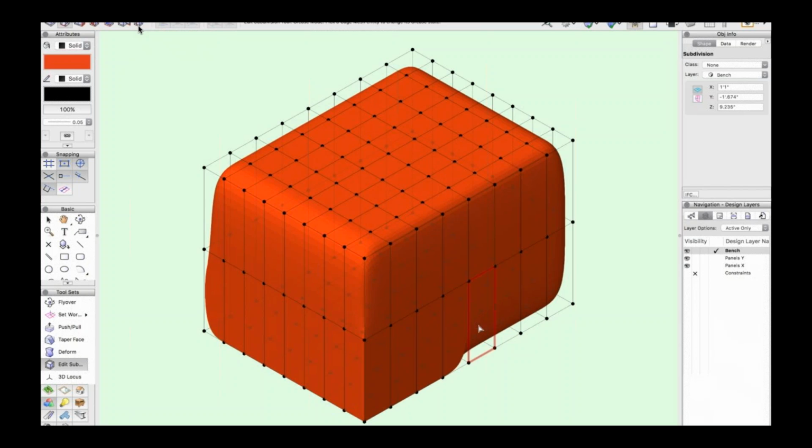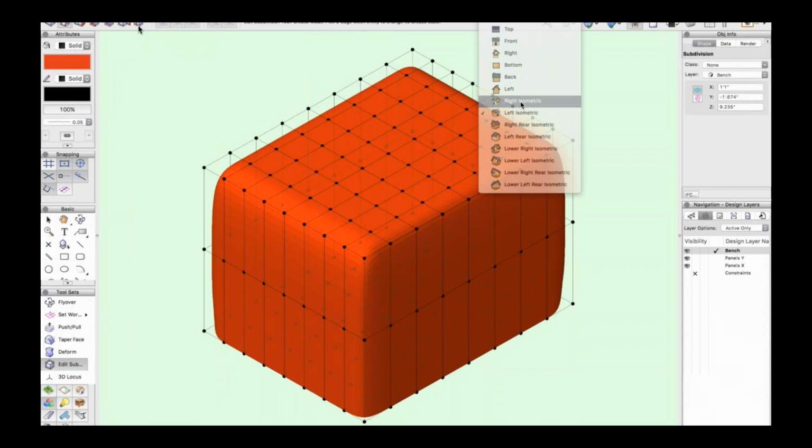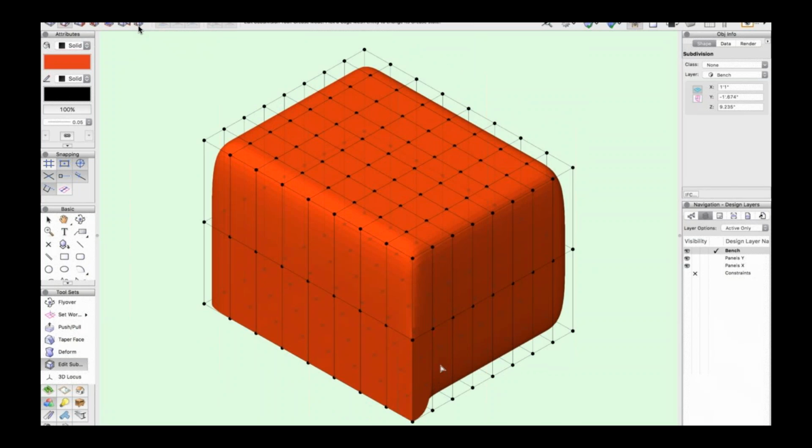And what I'm doing is clicking around the object and flattening that face right up to the cage. So that creases the face up to the cage. And then another thing is I can click on those edges and crease those edges right up to the cage as well. Well, why am I doing this in particular? I imagine that there might be a little bit more stability to my bench if it didn't have a rounded edge on the bottom, especially when I have all my clunky outdoor gear on. It might be nice to have a stable foundation to this particular bench. So I'm working my way around that object and essentially just creasing the bottom half of that particular object.